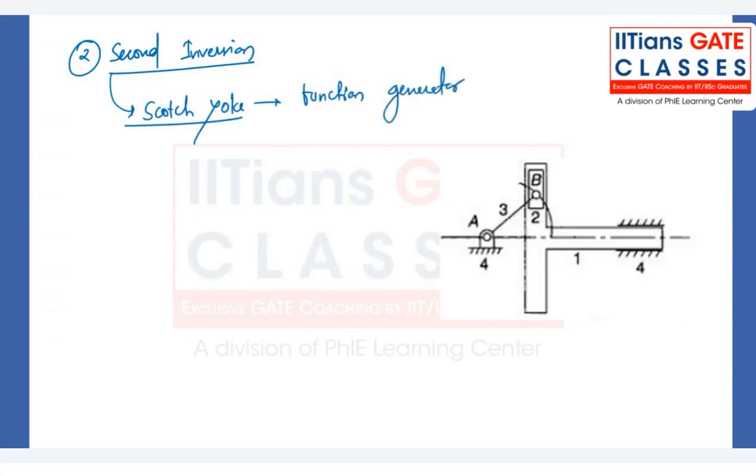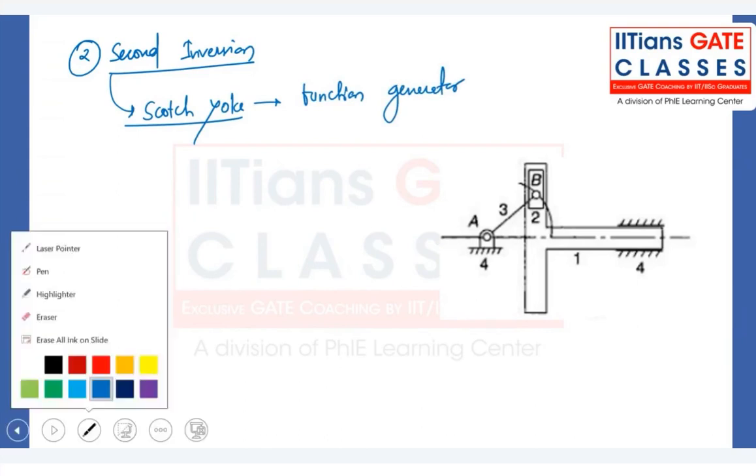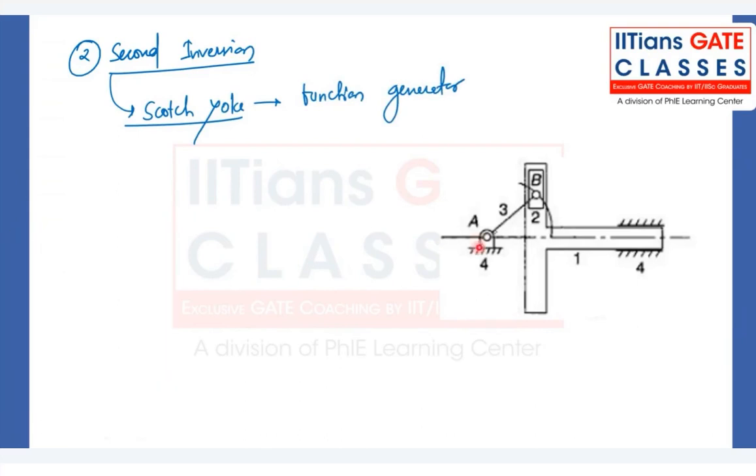look at this figure. As you are rotating this, link 2 is again a slider and link 4 is again a slider. This link 4 is also sliding here, left and right, and link 2 is also sliding in this slot. If you turn this link number 3 counterclockwise, the link number 4 will come towards the left hand side, right? Let me draw it here. If you bring it like this,